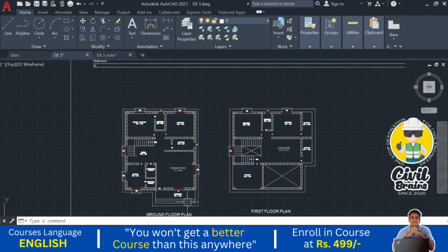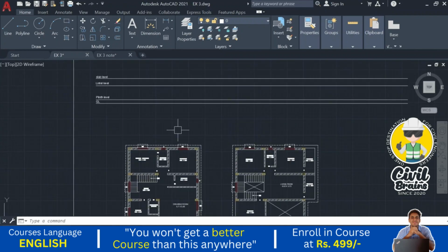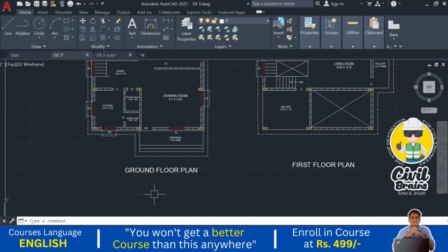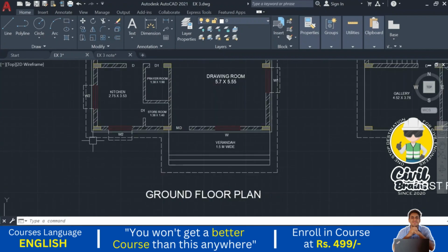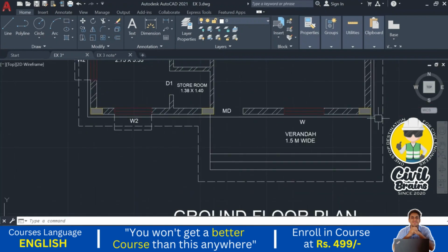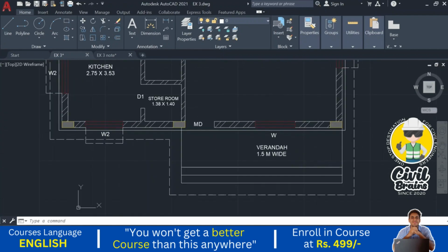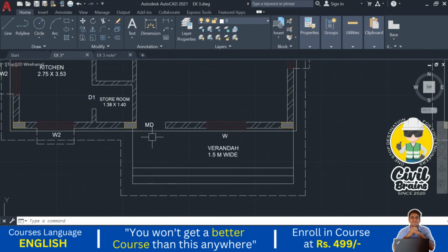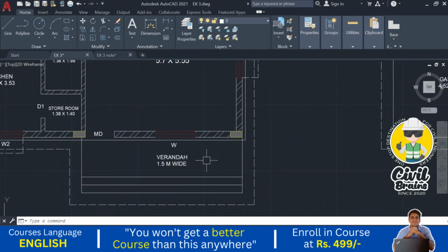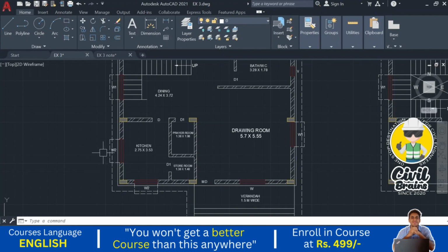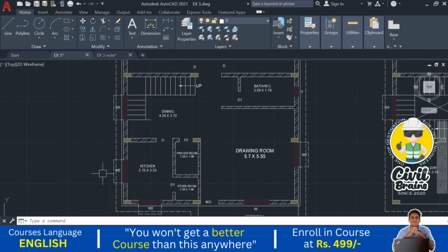Next we project the boundaries. So once we project the boundaries, we get that one. So if you come to the front elevation here, if you are standing in front of the building, what all things will you see? First thing, you see the plinth projection here on both sides, these corners. Next you see this window. Okay, these columns will be hidden. Next you see the main door. Next you see this window. Next, the slab projection you also see here, the veranda you see, the steps you see, and these two chhajja projections you also see, correct?